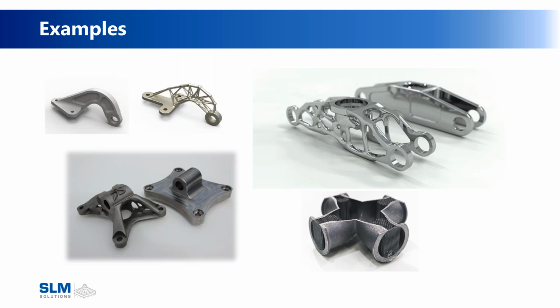And actually the bottom right-hand corner piece is a really cool piece, because this is a part that SLM Solutions produces for ourselves. Our gas tubing on our systems is all handled by DN40 vacuum fittings, which is what you see here. That DN40 vacuum fitting has very limited designs. So one of the areas that we do, it goes 4 pieces into one collector at the top. So we actually print our own 4-into-1 collectors for DN40 so that we're able to increase our design freedom of our systems, and we're printing the parts ourselves and making them for our own system.